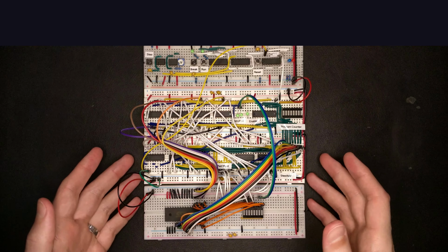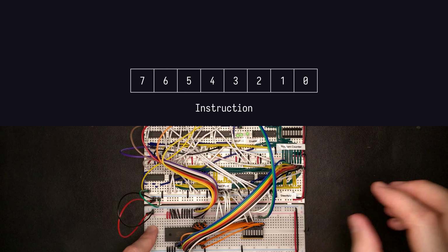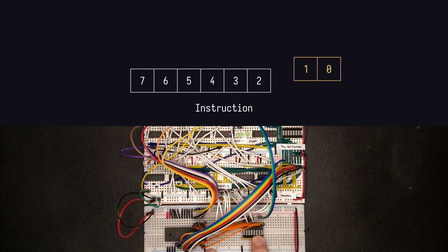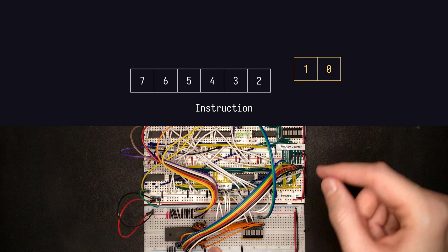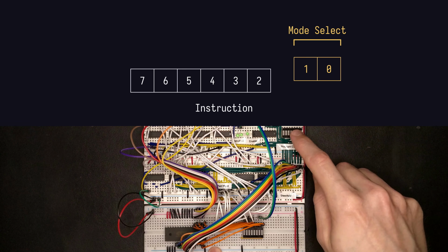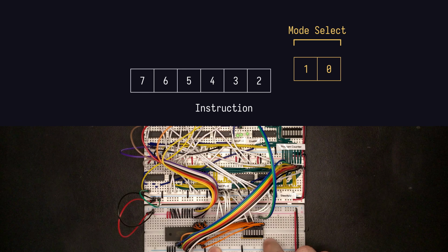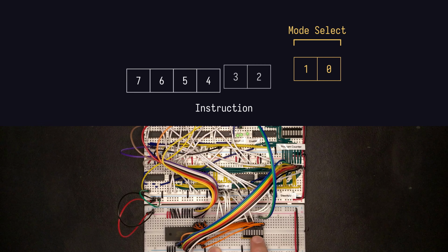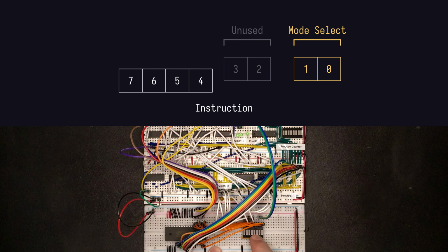All right, so that's hooked up. Basically, what we did is bits 0 and 1 of whatever comes out of memory is interpreted as the select lines to the program counter here. And bits 2 and 3 we left unconnected. These don't do anything at the moment.